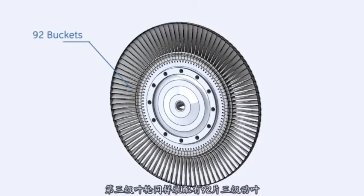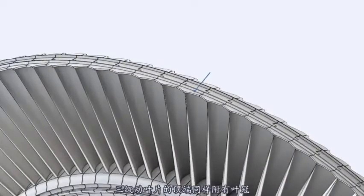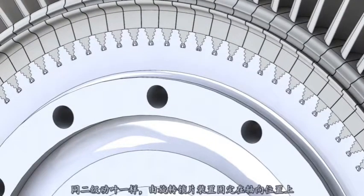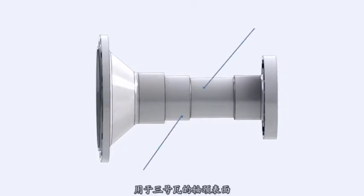92 buckets are also installed on the third wheel. Third stage buckets are not internally cooled. The third stage bucket tip is also enclosed by a shroud. Buckets are attached to the wheel by the dovetail arrangement and held in the axial direction by a twist lock arrangement, like the second stage. The aft wheel shaft is machined to provide the following features: journal surface for bearing number 3 and surfaces for oil and air seals,